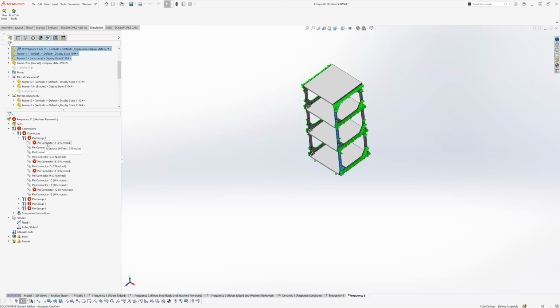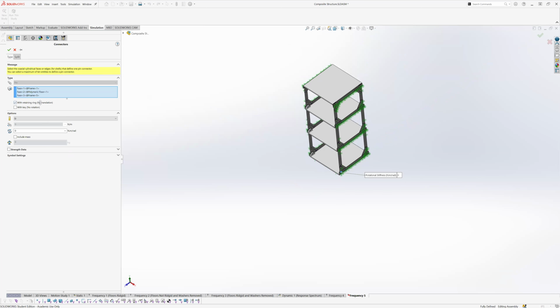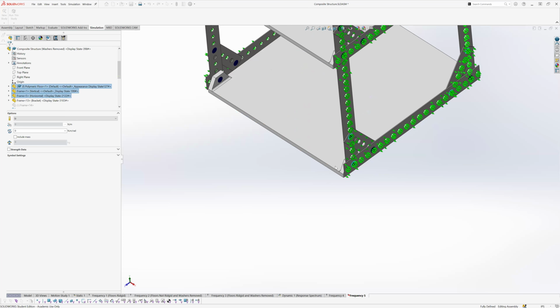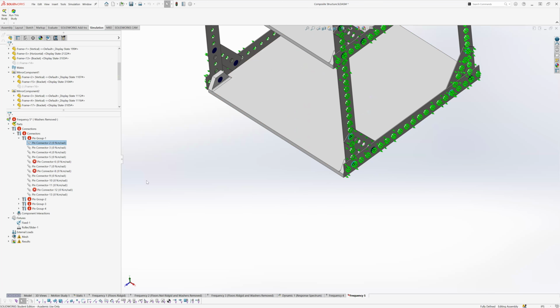So one thing you can do here is literally just right click here and edit these. If you notice, there used to be 4 faces. Now there are 3 faces. There's really nothing you need to do here. You can just go into them and hit accept, and that'll pretty much fix it, because it's looking for that face that's not there. It'll just say we're not going to bother with it.